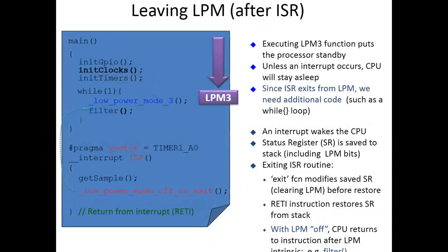And suppose you don't want to come back to the low power mode after executing some functionality, then you can do one thing. In the ISR, you can use this command called low power mode exit. In this way, low power mode can be turned off even after executing the interrupt, so it will be in active mode.